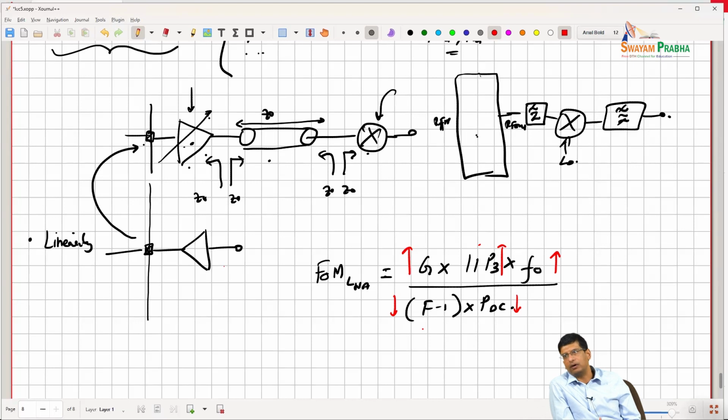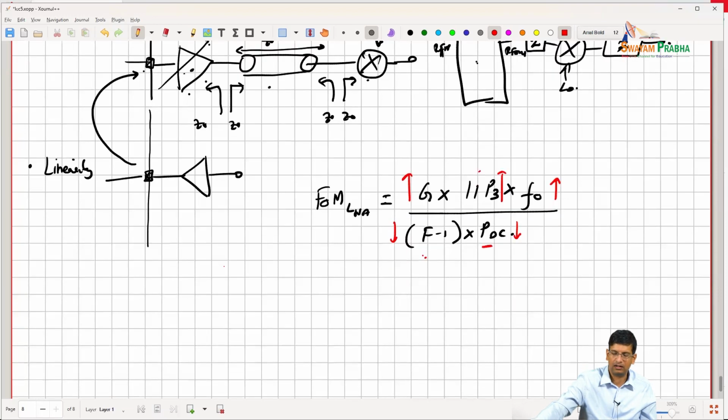Usually you burn power for dynamic range, right? So this PDC, you are burning not to get low F or low IIP3, you're sort of trying to burn it to get both F and IIP3 at the same time, right? So again, there's not a magic bullet to design here. You just design, see the trade-offs, and then build stages based on what the system calls for.